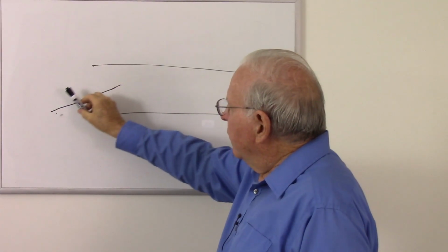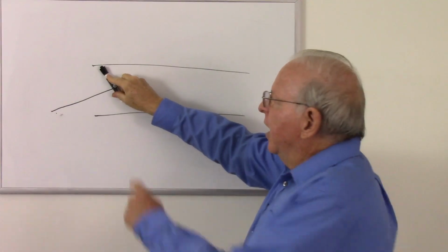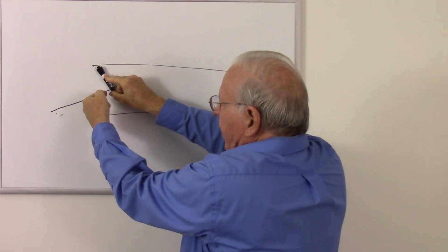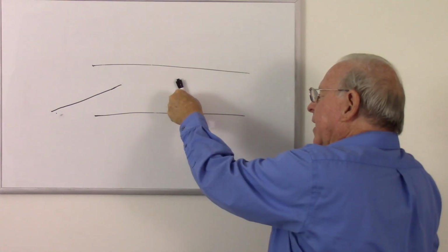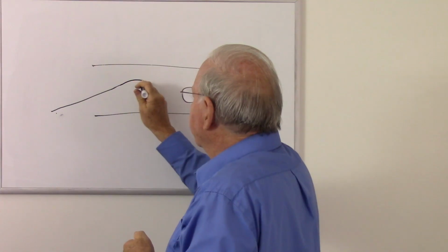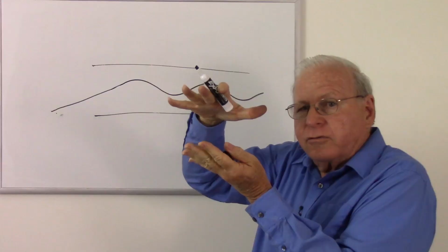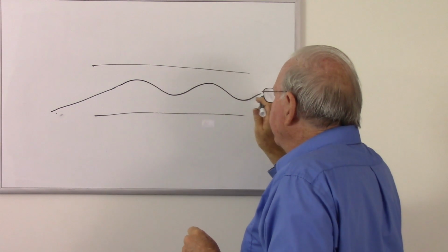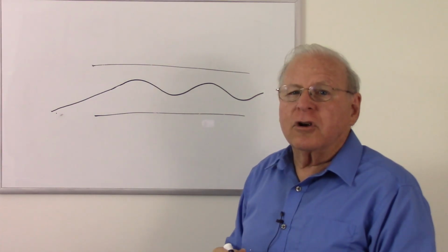As that light wave comes in, notice that this is a lower index of refraction here and a higher index of refraction there, so the light is going to travel faster on this side of the wave and slower on that side, so it's going to pivot. And it's going to go down like this, and it's going to pivot back again as it goes back and forth, and it never reaches the core cladding interface and just simply goes down in a serpentine path. So that actually confines the modes to a smaller area. So it's a lot like making a smaller core, but this keeps the waves near the center. And so this also mitigates the modal dispersion that we already talked about, and this is called graded index.